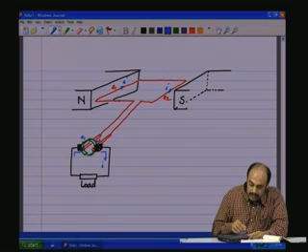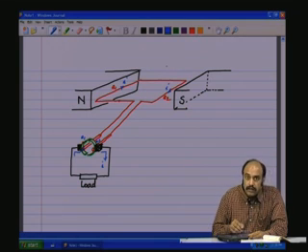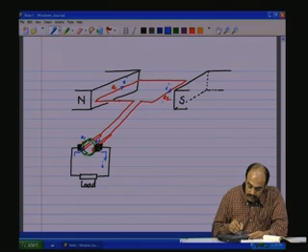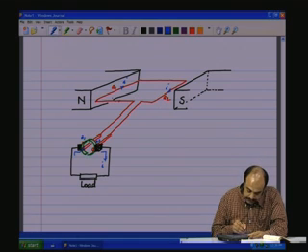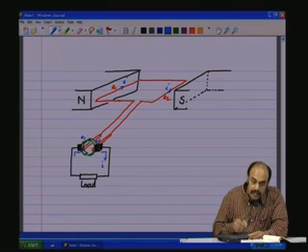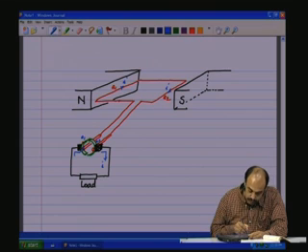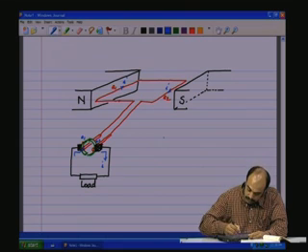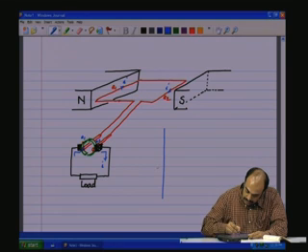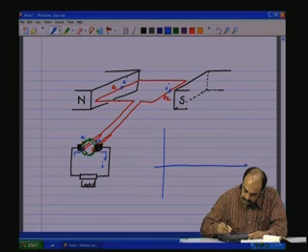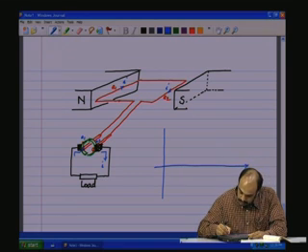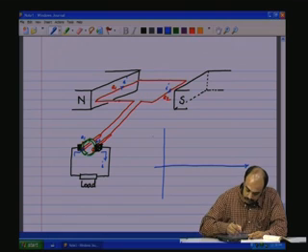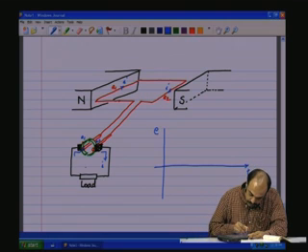But at that point, when it has crossed over the orthogonal plane, there is a reversal in the current for A2 and A1, and therefore A2 becomes positive and A1 becomes negative. So therefore you would see in the time axis, temporal axis, time versus the induced EMF E here.